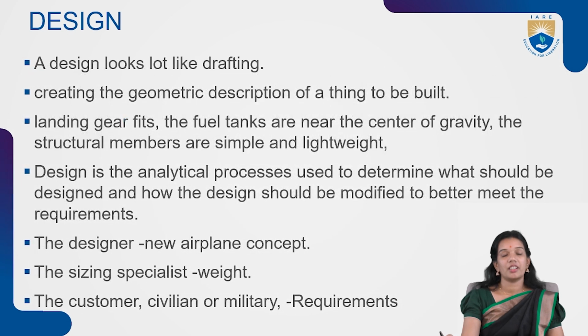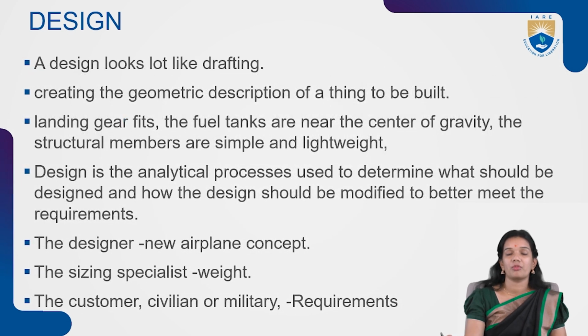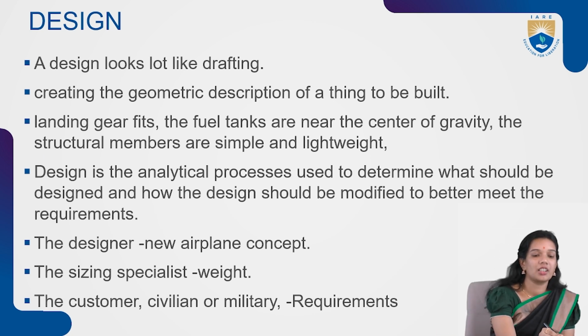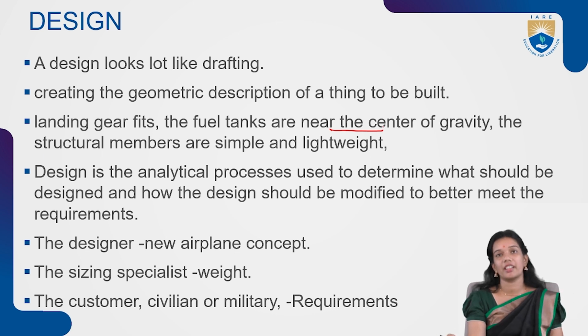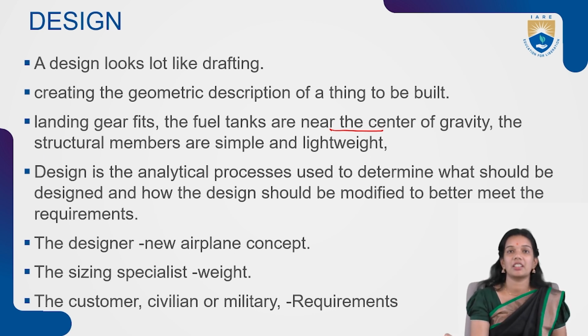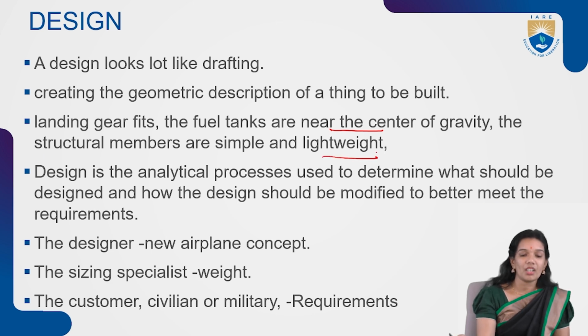So a design would look more like drafting, or computer aided drafting, we can say. Design is done by creating a geometric description of a thing that we build. So the designer makes sure that when he is designing, the landing gear is going to fit, the fuel tanks are near the CG, and he also designs a structural member such that it is very simple and light in weight, because weight is an important factor in an aircraft.